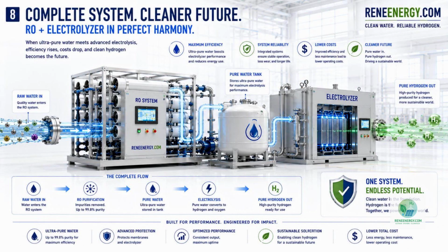Image 8 brings the full system together. Raw water enters the RO system. Impurities are removed. Pure water is stored and delivered. The electrolyzer receives high-quality water. Hydrogen exits the system. This image is the payoff because it shows the full chain working as one integrated industrial platform. The lesson is simple but powerful. Green hydrogen is not created by one machine. It is created by a system of systems. Reverse osmosis protects the water quality, which protects the electrolyzer. The electrolyzer produces hydrogen, and the entire system depends on every hidden layer doing its job.